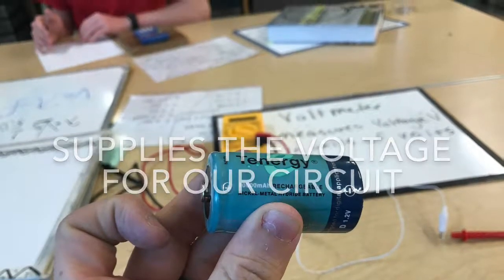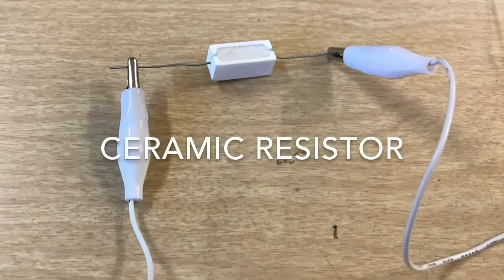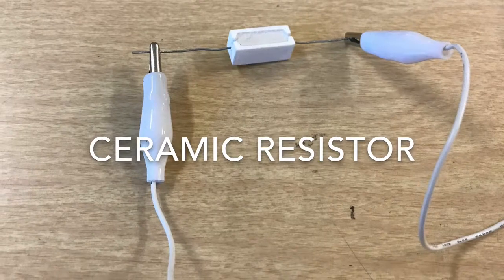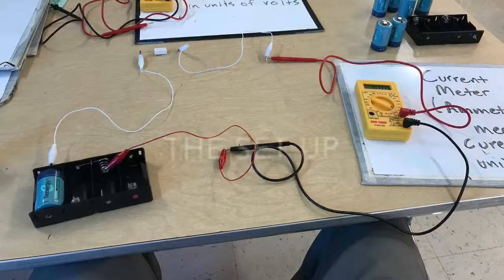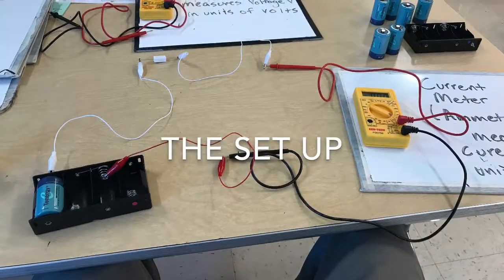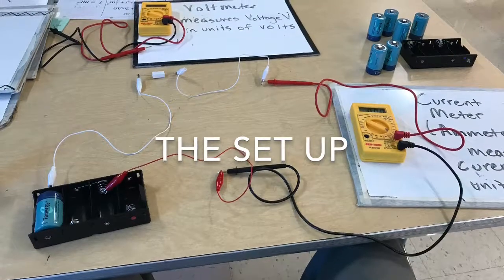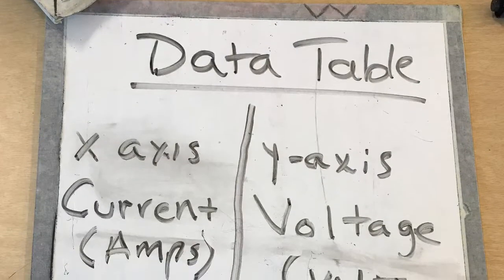The battery that we'll be putting in will supply the voltage or the potential difference for our circuit. That's what's going to drive the charges around. And we're going to be sending them through this ceramic resistor. The charges will flow through that and heat up that material. And so the overall setup of our circuit looks like this. Our current meter will measure the current for us through the wire. The voltmeter will measure voltage across that resistor.